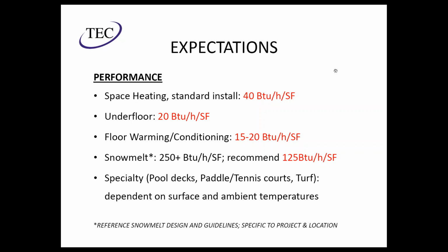All right, as far as what load you can expect to extract from a slab, it all has to do with the temperature gradient between the space, the water that's supplying it, and the surface temperature that you're accommodating. As I just mentioned, in space heating, our typical surface temperature is a max of 85 degrees, I believe, but that's regulated by ASHRAE.